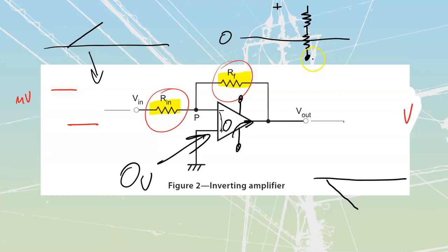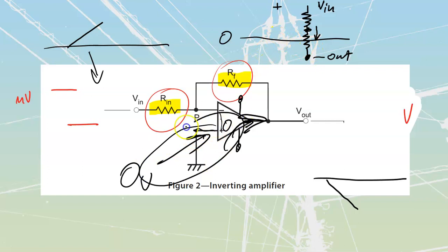across. One of these is going to be attached to my output. That's going to be the far end of RF over here. That's my output over there. This one over here is my Vin that I have up top over here. This common point over here, what the op amp is going to do is continue to drive negative values of voltage out, because it is trying to pull this down until eventually I get to this point where I'm going to have that common point back to that value of 0, because that's what it's trying to do. It's trying to balance to this one over here.